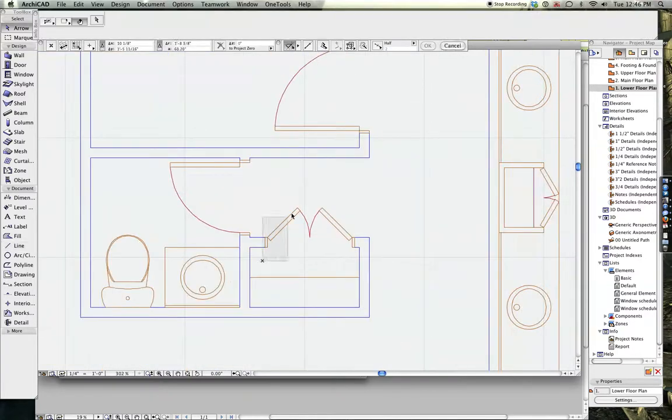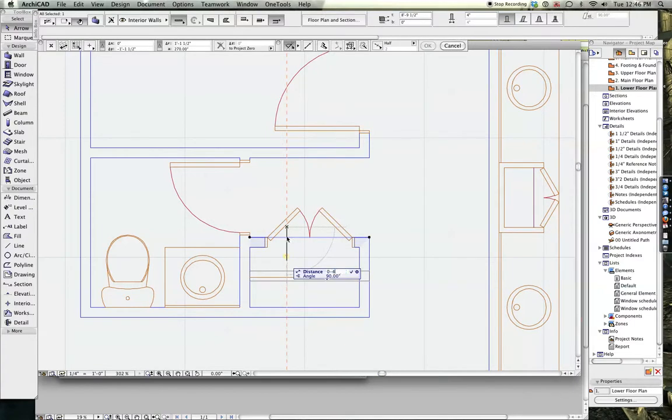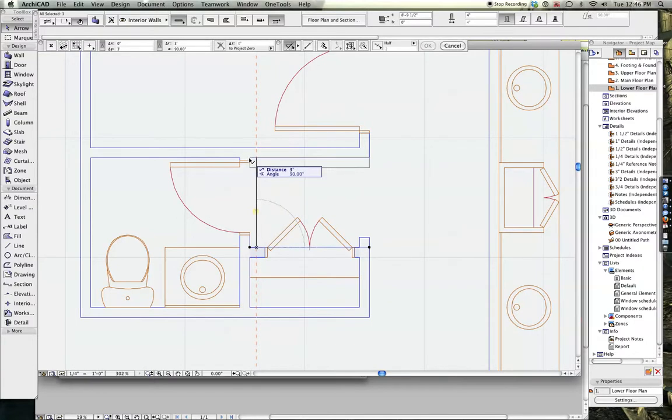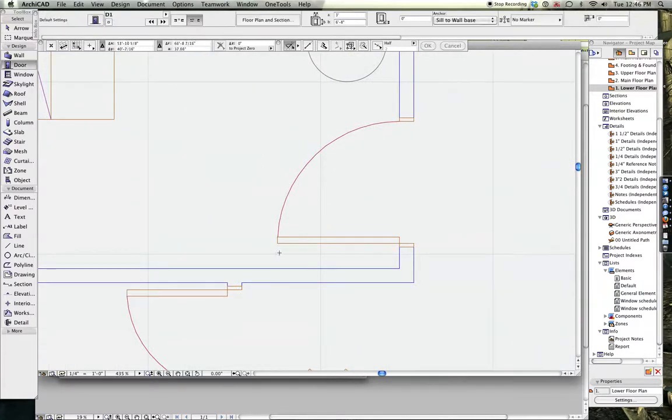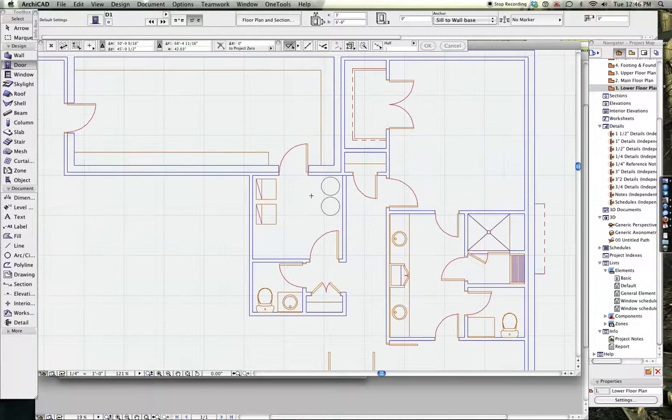You know what, since this is just a small closet, we're going to copy that out. We're going to move that out 4 inches. It'll give us 3 feet here. That'll just work a little bit better, I think. Okay, now this door actually is supposed to be on this wall right here. Let's just move that back into place, because I had it on the center anchor tool. So you hit Command D and the D key again to center it, and it just moves it in. Then we can just delete that guy out of there, and there you go, you're done.